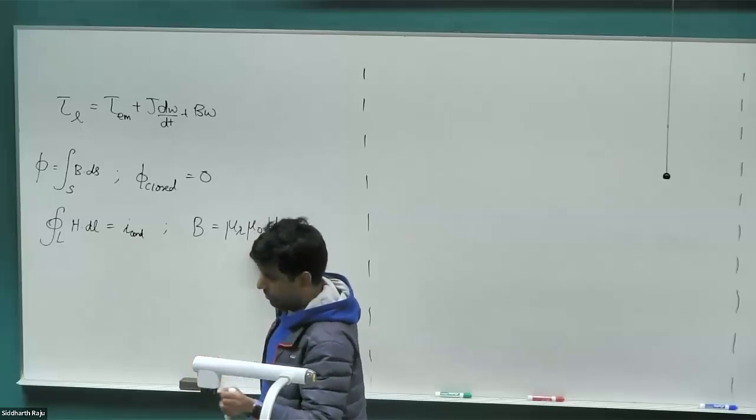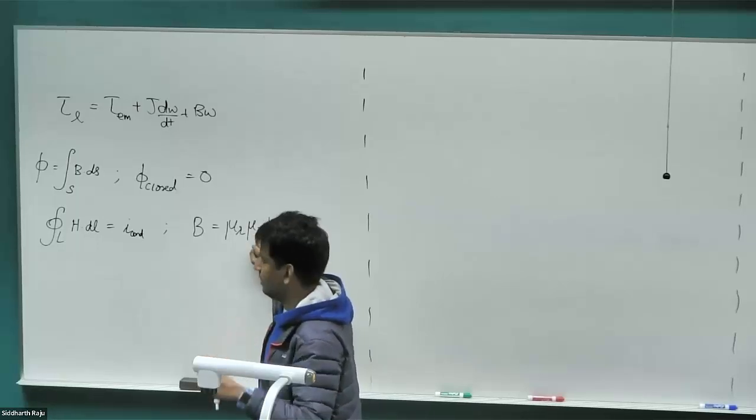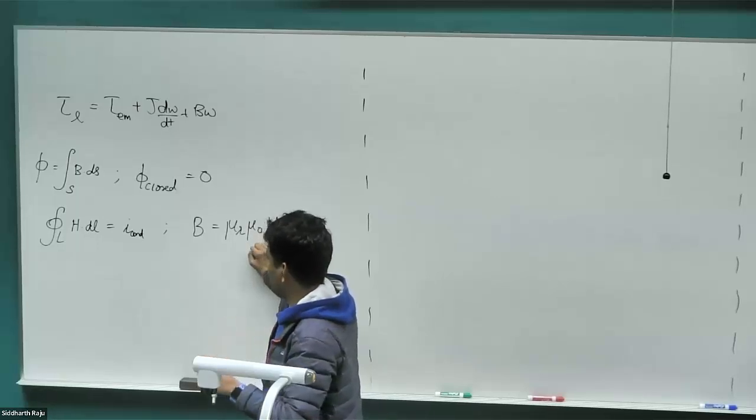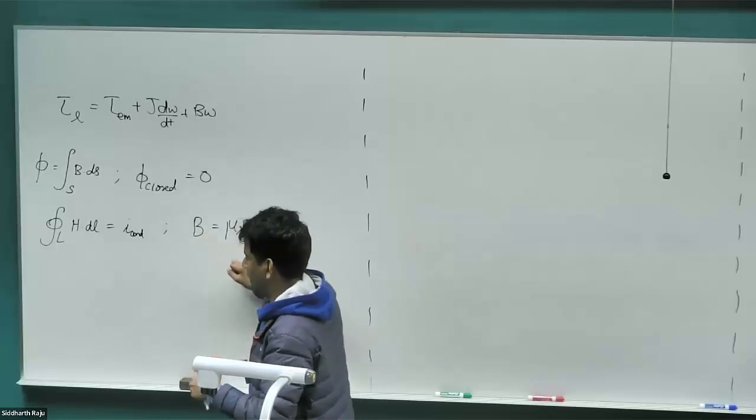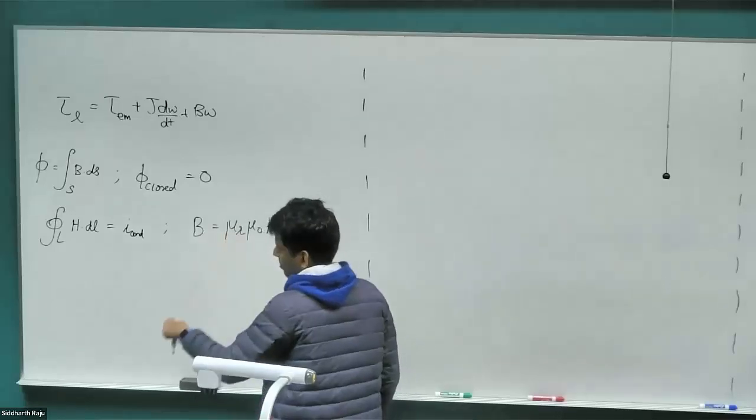In reality, in motors, iron would be operated somewhat well into saturation in certain parts, like the teeth of the rotor and stuff like that. But for our consideration, we can just assume it's not saturated. Right? If that's the case, then we can just assume it's a constant.